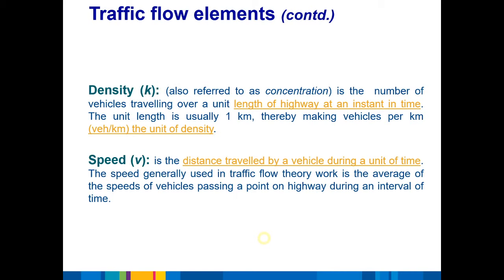And that can tell you things about the roadside environment. People might see an 80 kilometer an hour speed limit, but they also see a very wide stretch of road with a very straight alignment, good viewpoints, no intersections, and they think this doesn't feel like an 80 kilometer an hour speed limit. So the road environment and the speed limit need to match, otherwise the speed of vehicles won't really match the speed limit. Hayden, is there anything you'd like to add on to that one?